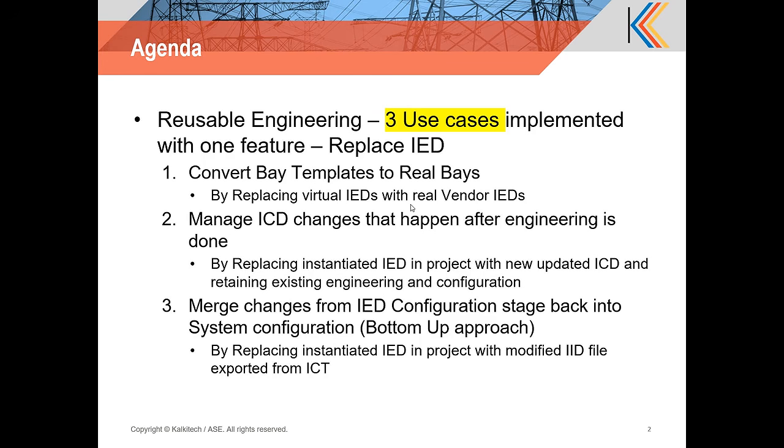Using this method, you can do a lot more than a conventional SSD. In a conventional SSD, you just have single line diagrams and functions, but here those functions can be referenced to these virtual IEDs, and you can perform complete engineering of those virtual IEDs with respect to datasets, reports, rules, and signal mappings. Now this bay template is incomplete without the second stage, that is to replace that bay template with real IEDs in an automated manner. And that is the use case that we will demonstrate first with the replace IED feature.